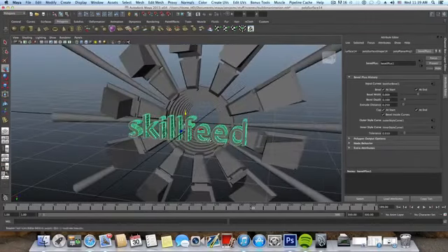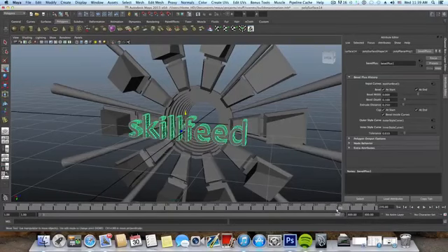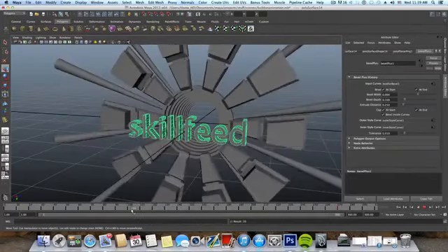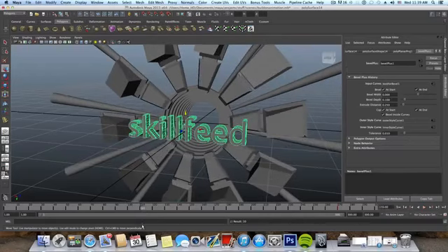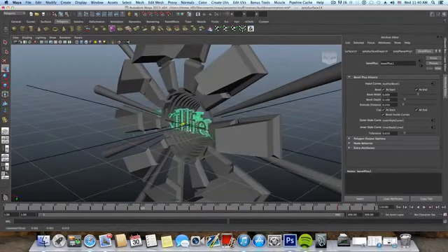I will set it to frame number 270, and press S key to record this. Now I can decide when I want this to appear. So I can make it appear on frame number 110, and basically I will just choose the frame, move this to the back like so. Press the S key to record this movement.